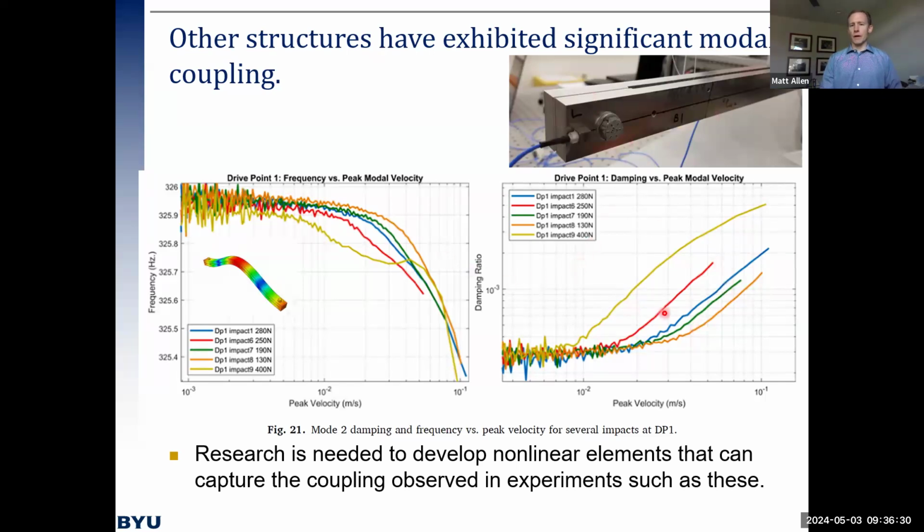Even in this case, though, we do find the modal approach to be helpful, because there's usually a minimum value in the damping and a maximum value in the frequency over a set of measurements. And you can assume that that minimum and maximum value is the uncoupled mode case, or that's the case where the contributions from other modes are minimal. There are some assumptions there, but in many cases, when all the nonlinearities are damping nonlinearities, that works well. And so you can tune a model using that backbone curve and the modal approach, even though mode coupling exists for other scenarios.